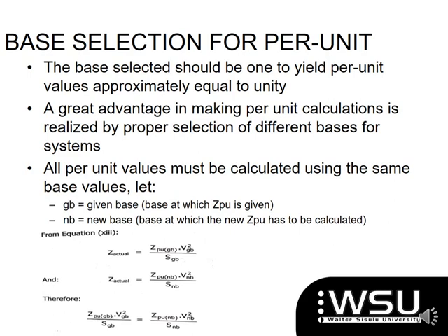And sometimes that impedance could be in ohms or it could be in per unit. You still need to change it, even if it wasn't per unit, into a new per unit value. And you do that by utilizing the formulas that would have changed it into a per unit. And we are going to see, hopefully, some of those examples as we go further.